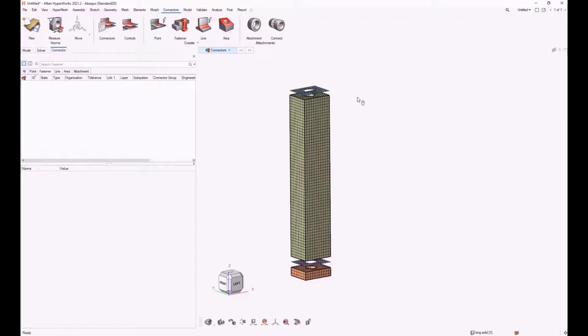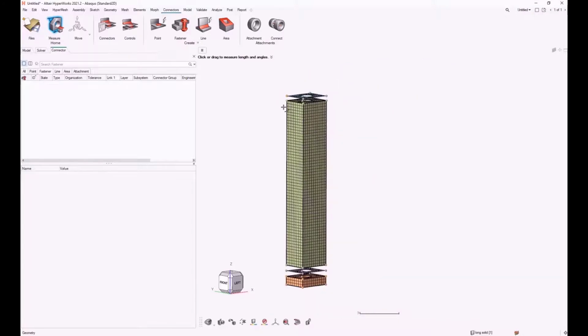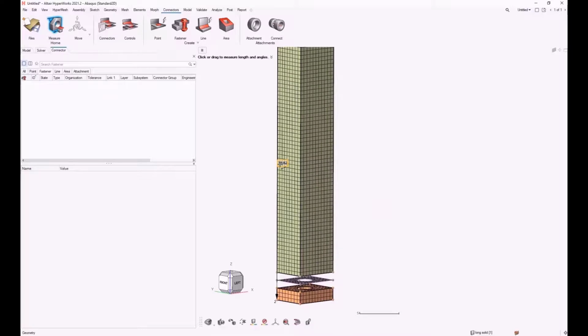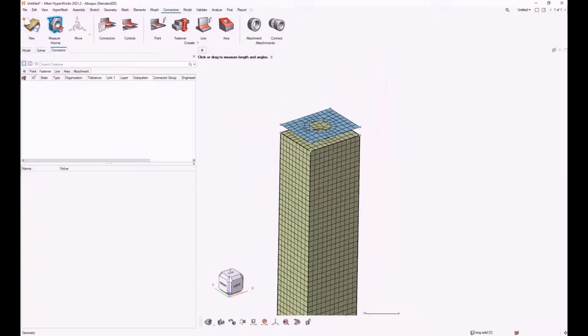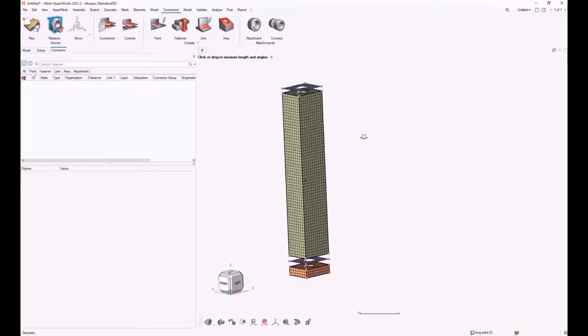So in this video, we're going to create a fastener connector through a long span, multiple layers, and differing element types. So our total span from about that top to that bottom here is approximately 34. And our diameter is 2. And we've got a total of 1, 2, 3, 4 layers.